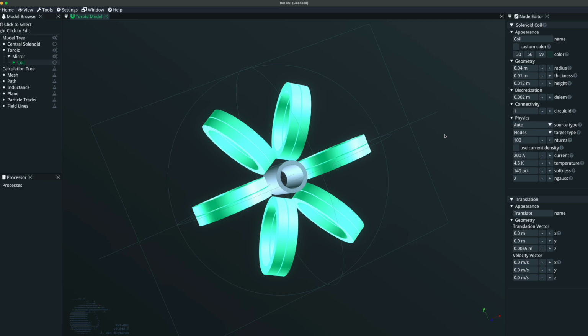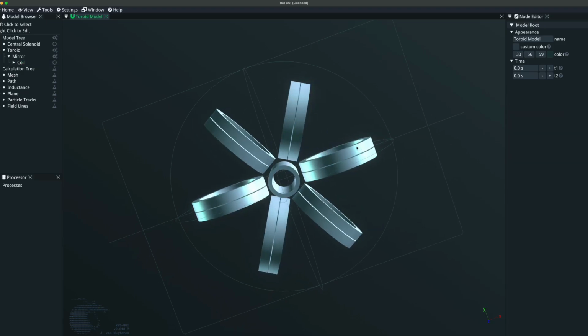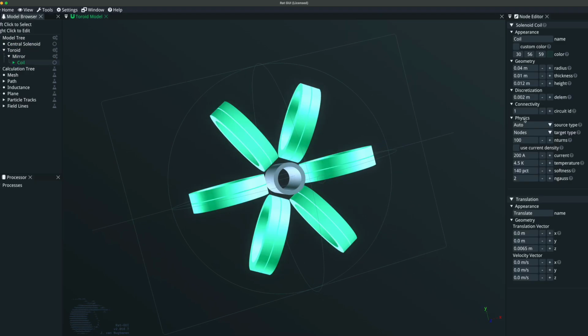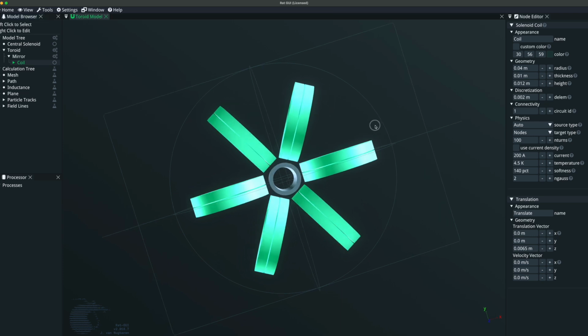However, the auto setting also does not always select the most accurate, but it takes into account the combination of accuracy and speed, because usually when you're designing your magnet, you don't want to spend endless time waiting for the calculations to be finished. So the auto setting picks the best setting that is the fastest and the most accurate, and that doesn't always mean it gives you the best peak field.